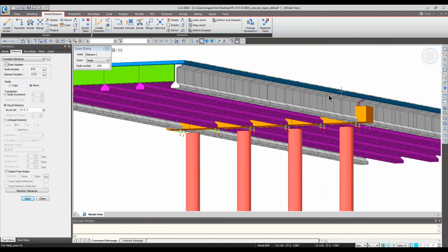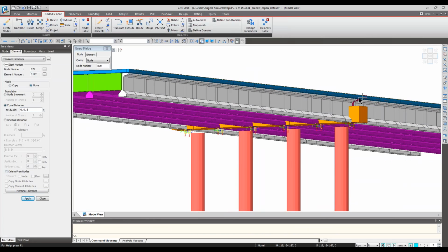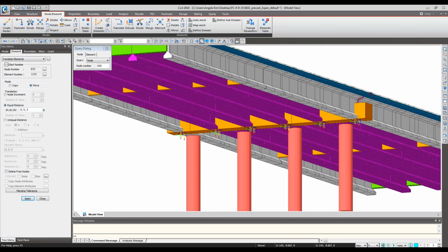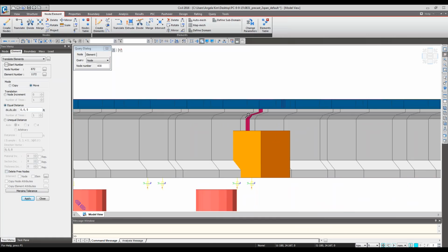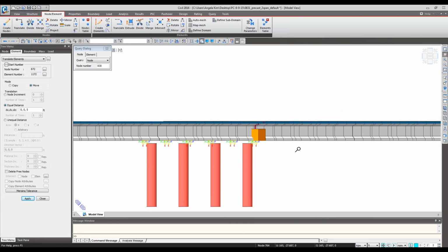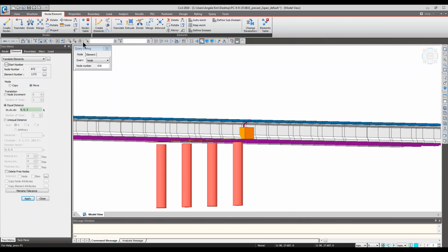And this may be coming down all the way from the deck, just poured once. You can reflect that by increasing the size of it. It's exactly the same way we can change the section property right here. And this pier is now hanging in the air, but no worries. We can, of course, change the node coordinate for this pier cap too.